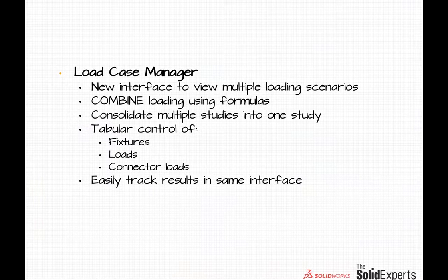This makes it very, very simple to set up a large number of loading conditions in one easy-to-use table, as opposed to setting up multiple studies using tabs along the bottom of your screen, like we're all used to doing. Now it can all be managed in the same table in one study. There's multiple filters as well for focusing just on different options like the fixtures, loads, and connector loads. This is all managed in the same interface.